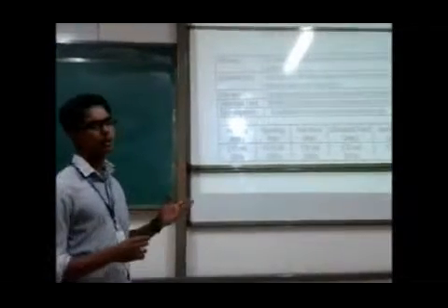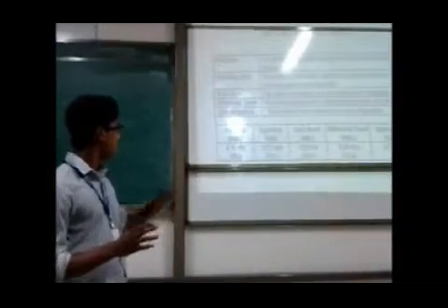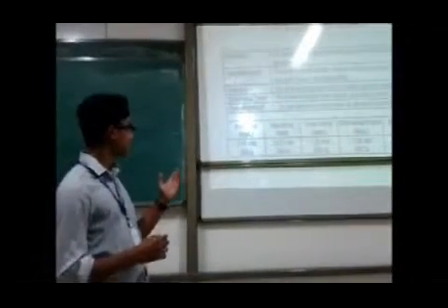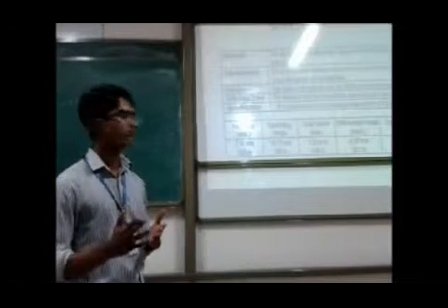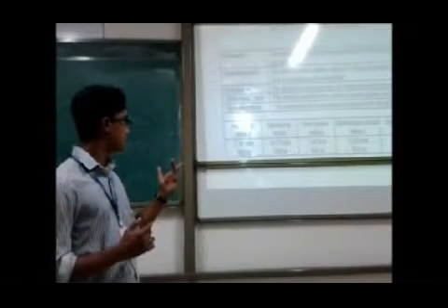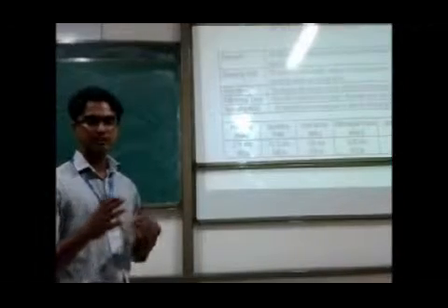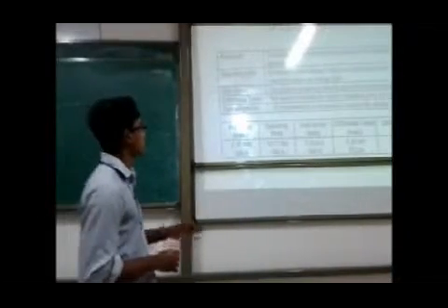These are some of the specifications of the mechanically operated solid state switches. The free travel is the distance the switch plunger moves from free position to operating mode, and operating mode is the mode at which all operation starts. Overtravel is the distance the plunger has traveled after going past the operating mode. Differential length is the distance between the operating point and the release point. Operating force is the mechanical force which is necessary to depress the plunger.